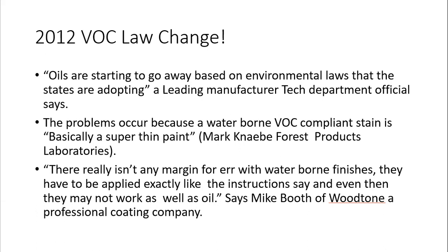All right. So here you go from stains that have been used the same way for years, an expectation even I got caught on, and they change the application so extremely. The change in application between oil-based and film forming is so extreme that it should be highlighted with a giant warning sign, and nobody knows anything about it. All right, so that is what has been causing all of these failures. Number one reason for the failures is this VOC law change: manufacturers changing their formulations without a sufficient warning system for the people who had been using their stains for years.